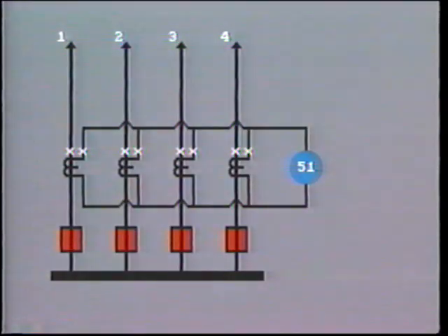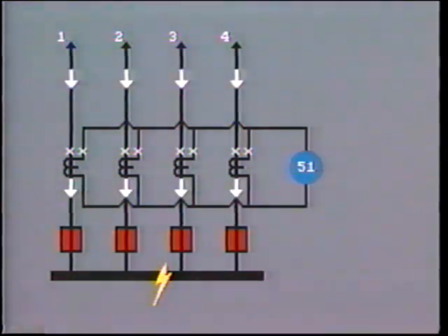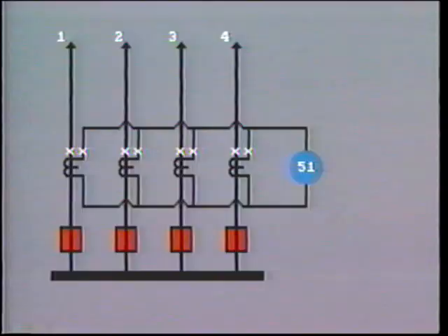In practice, this accuracy is difficult to achieve, especially where the measured currents are of greatly different values. This would not be such a problem with operation due to a fault on the bus, because the current in all of the connected circuits now feeding into the bus would be of a similar magnitude. However, in the case of a through fault, this CT unbalance or error current could cause inadvertent operation. You'll remember that we have discussed this in earlier videotapes.